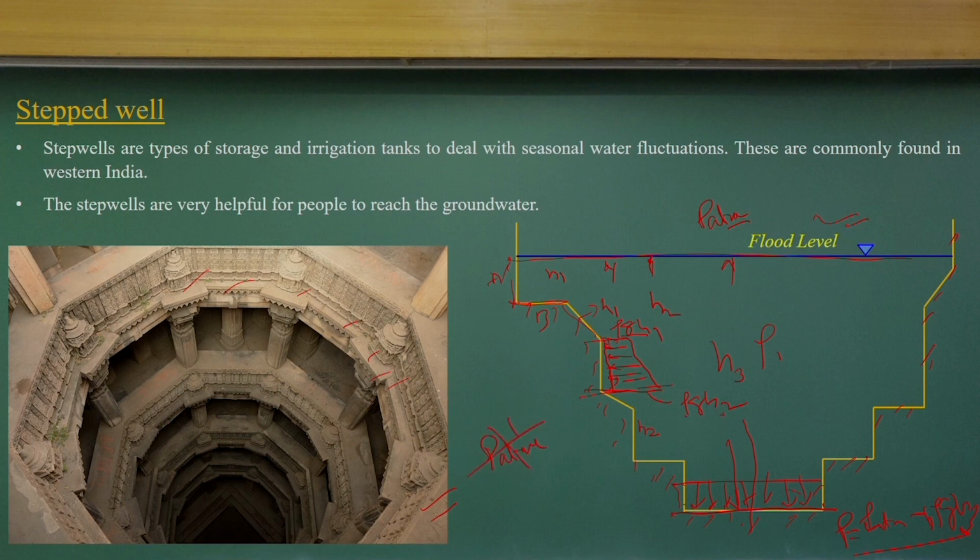We are neglecting that as compared to the pressure from the water, which has a much higher density than the atmosphere. So, we can get the pressure diagram, which will be trapezoidal, and if I know this pressure diagram, I can compute the total force acting due to it, which is a very simplified thing: find the area of the pressure diagram, multiplied by the perpendicular distance, which many times we consider as unit distance. Then the area of these diagrams will tell me the force acting because of these pressures.